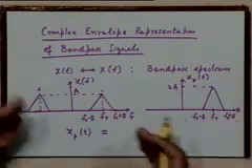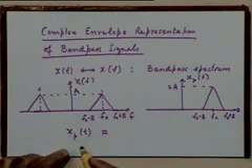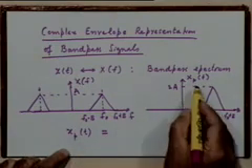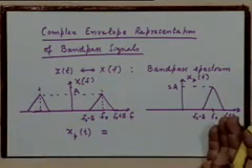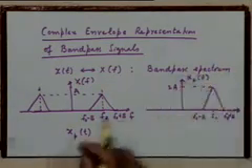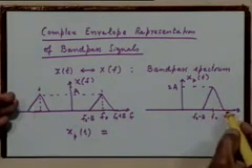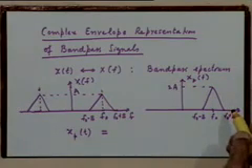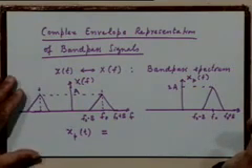And how do you do frequency translation? By f0 only, by multiplying it with an exponential, right? So therefore it stands to reason that I could represent this xpt as a frequency translated version of some low pass signal whose spectrum is this, right? Will that be symmetrical? May not be symmetrical. That will depend on whether this is symmetrical. Therefore that signal may not be real. It can be complex.